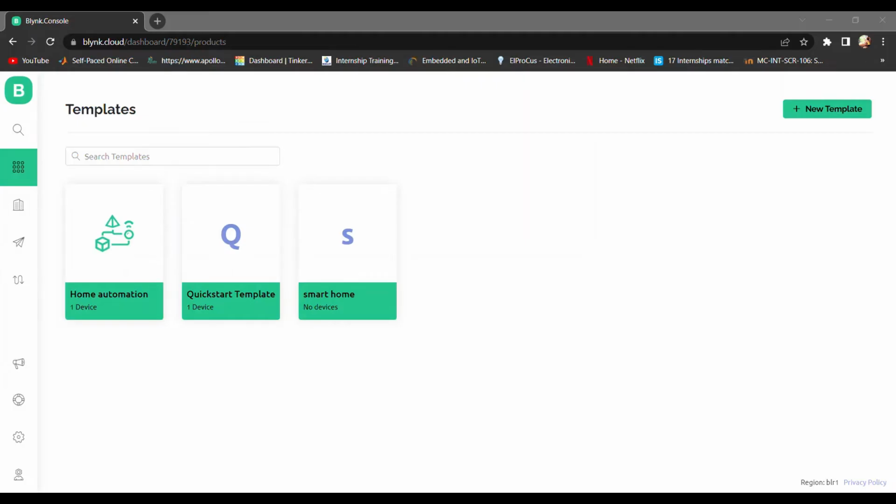For our convenience, we can use Blynk on browser. Search Blynk Cloud on Google and visit the first link on it. Create an account in there, then go to the template icon, which is in here, and then create a new template by giving the corresponding details. Don't forget to note down the template ID, device name, and the authentication token, because we need those when we are coding.